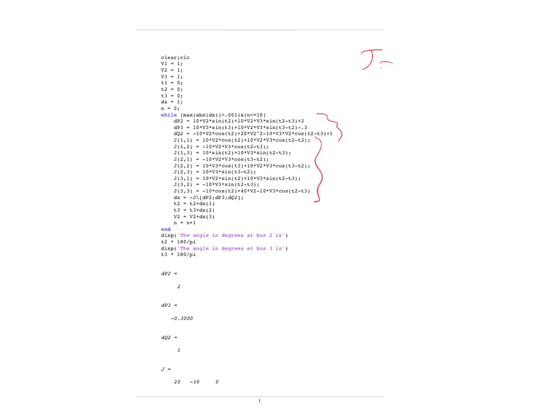So remember our Jacobian is delta P2, delta P3, and delta Q2, right? Because bus 2 is the load bus. So then I have theta 2, theta 3, and V2. Notice I always put my P's and thetas and V's together, even if it goes out of sequence.